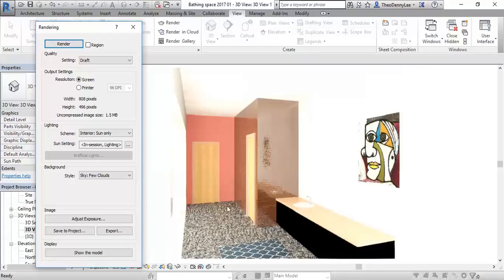Yeah, it does. The colours, that's right. So what's wrong with the colours overall? Maybe looking over here especially. Way overlight. That's right. It's too bright or overexposed. But yeah, over is a good way to think of it. So if you look down the bottom in this render dialog box, you'll see you've got the option to adjust exposure.